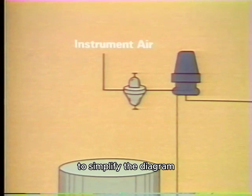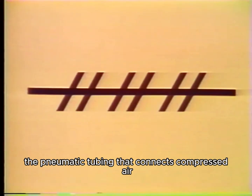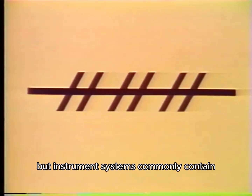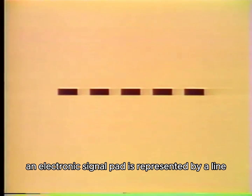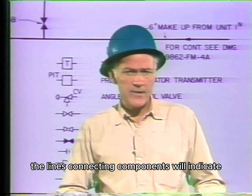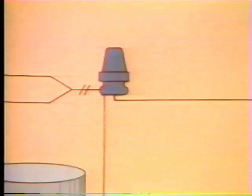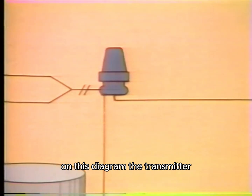To simplify the diagram, this symbol will represent a compressed air system. The pneumatic tubing that connects compressed air systems to various instruments is symbolized by a line with hash marks. But instrument systems commonly contain electronic instruments as well. An electronic signal path is represented by a line like this one. We mention this because when reading plant system diagrams, the lines connecting components will indicate the type of component or instrument you're dealing with. Okay, let's look at the first instrument group on this diagram, the transmitter.